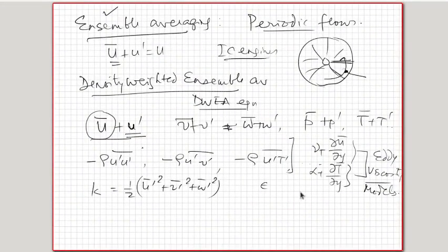Okay, so these Eddy viscosity models basically assume that whether the fluctuation is in this direction, or in this direction, they cause the same value of nu t. So the eddy viscosity caused by the fluctuations in x direction, let us say, y direction and z direction, result in the same value of nu t.